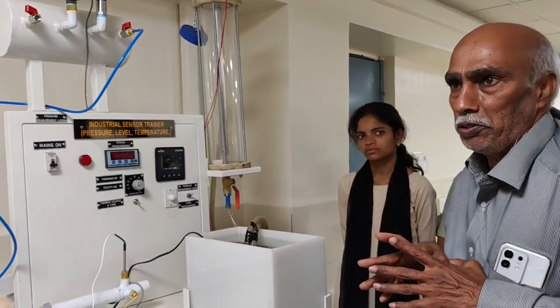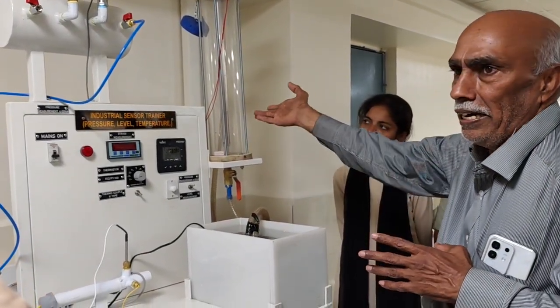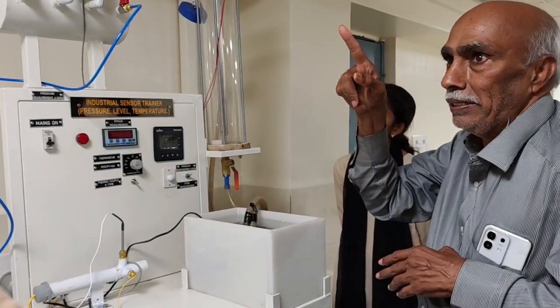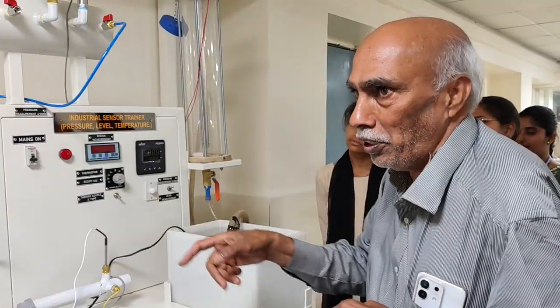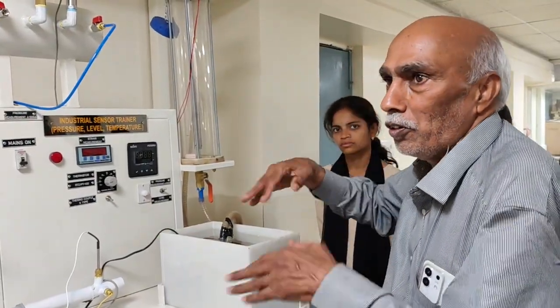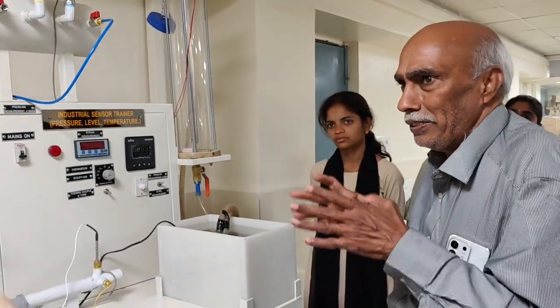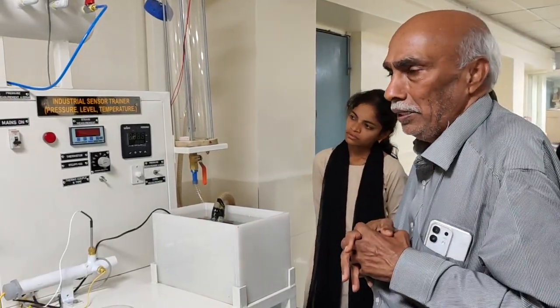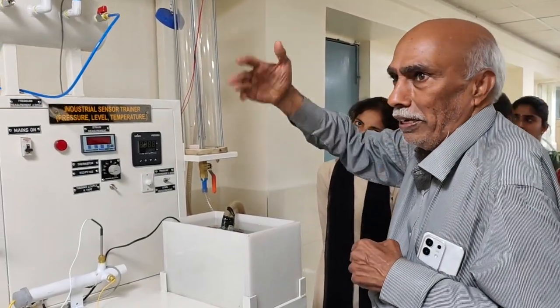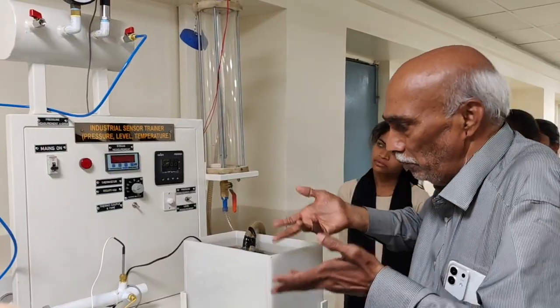There also again it is 20 milliamps only. So 200, 100, whatever you set. Once the milk level reaches 200, the pump will automatically stop. The operator will not have to go and switch it off. What will happen if you forget it? Milk will overflow, some problem will come. In the automation industry nowadays, more or less, it should operate automatically. Once the milk or whatever oil level comes below 200, it will pump.